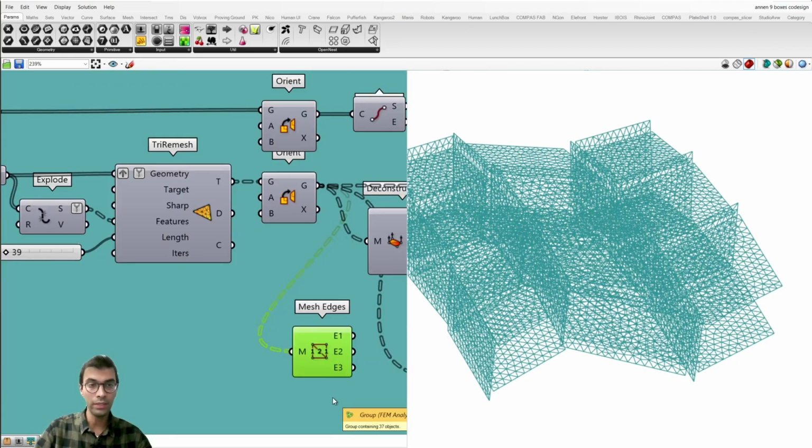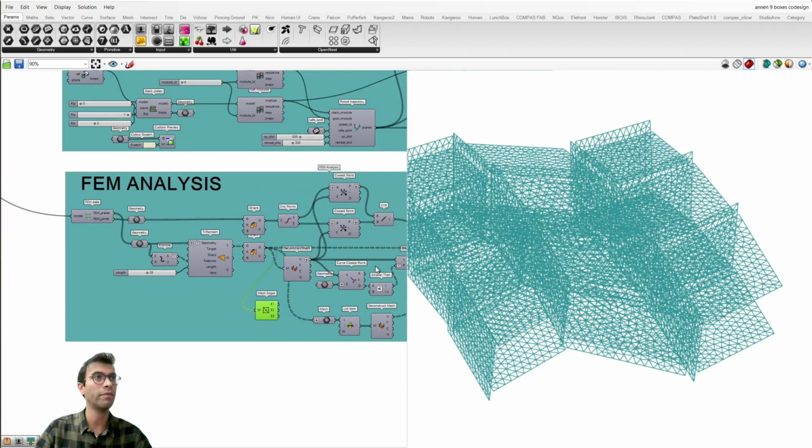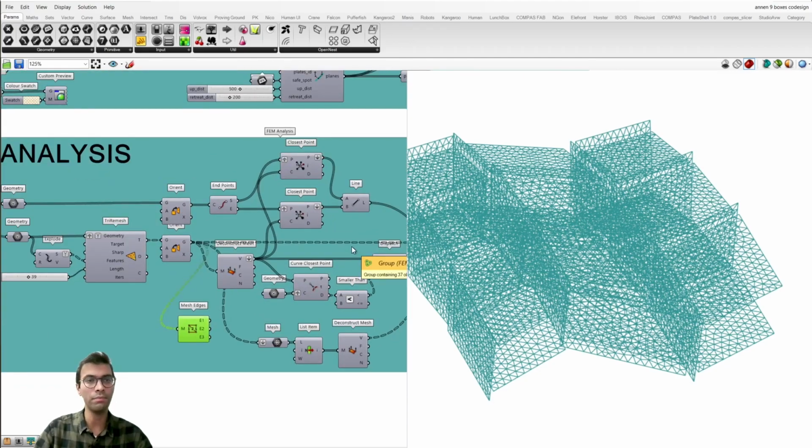As I already explained in my previous slides, one of the required steps for finite element simulation is to define boundary conditions and loads. Here in the Grasshopper environment, we've already used some Grasshopper components to isolate those points and those areas in our structural system, in order to define boundary conditions and also loading points. So far, we have talked about the input geometry required for finite element analysis, such as the mesh for timber plates and beam elements to represent connections.